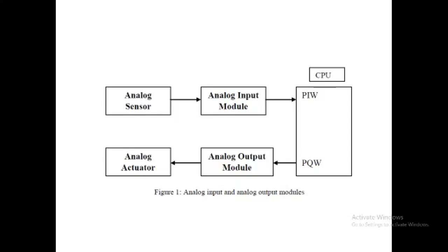In general, the values read from an analog input are stored in a memory word, and sometimes you are required to convert these values to an appropriate format to use them in a program in order to make a correct decision according to the actual input voltage.